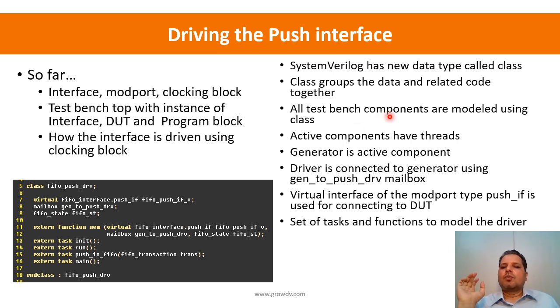That is why the driver is an active component and it will have its own thread. In SystemVerilog, we have seen fork based launching of procedural code. It will have one thread because it has independent existence. It can receive FIFO transactions and process and drive them. So it has to have that independent existence, it will have internally a thread, and we will look at it in a little more detail further.